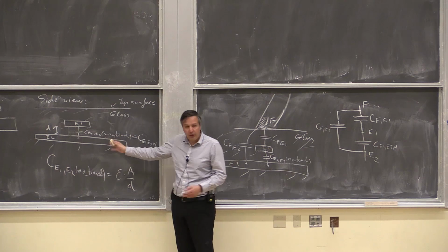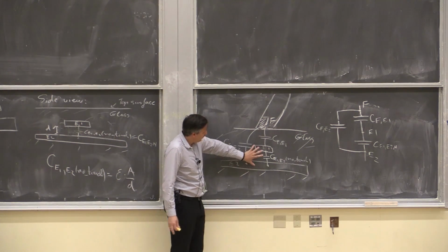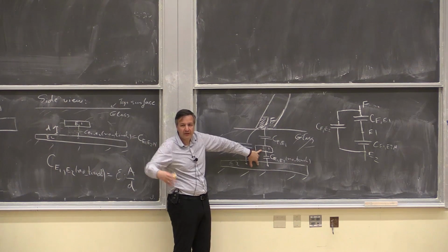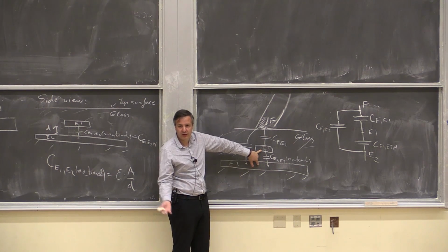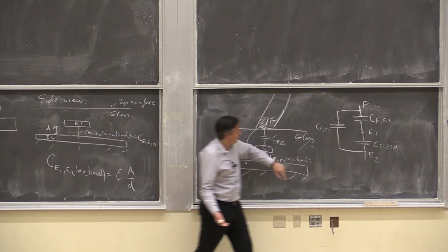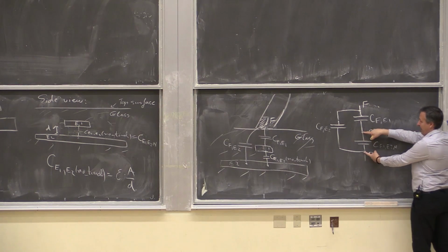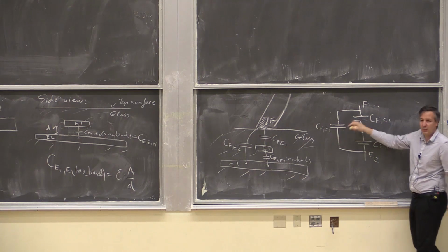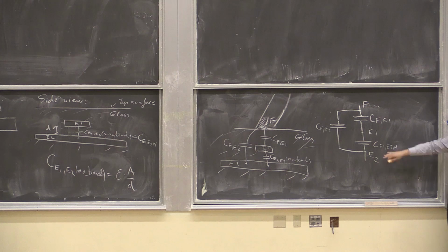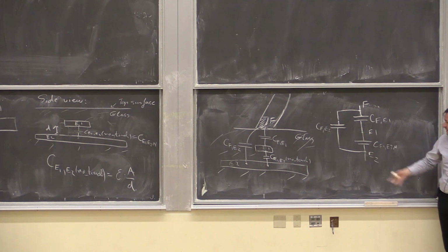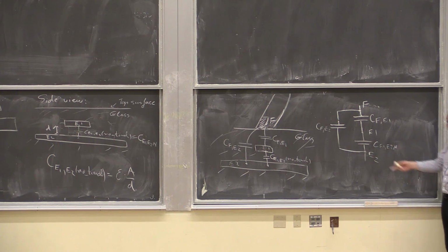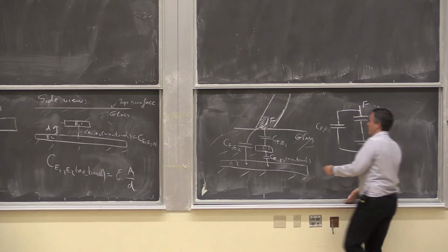This setup is really cute because I only will put my measurement circuit between E1 and E2. I don't have to worry whether the finger is grounded or not or anything. Right? So my circuit will look at what happens between these two nodes, E1 and E2. Notice that the finger node is just between these two capacitors. Okay? So I want to redraw this circuit so that I can more easily see what is the equivalent capacitance between nodes E1 and E2. Okay. So let's do that.